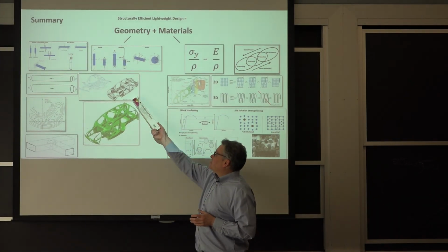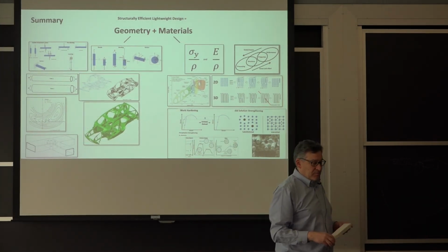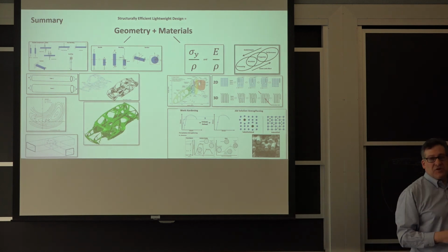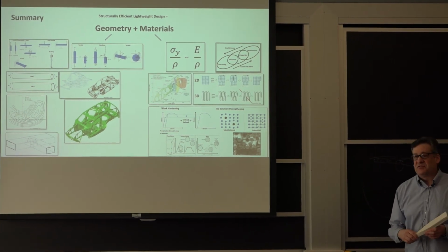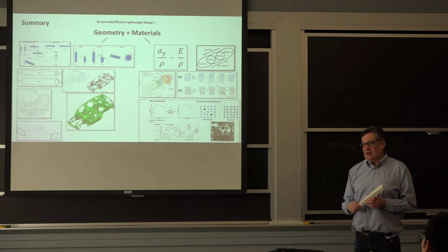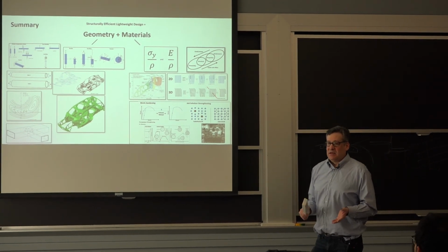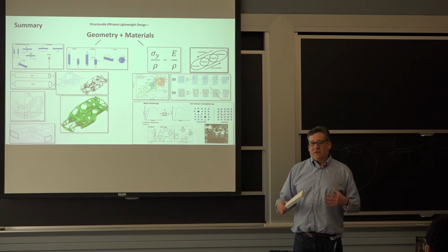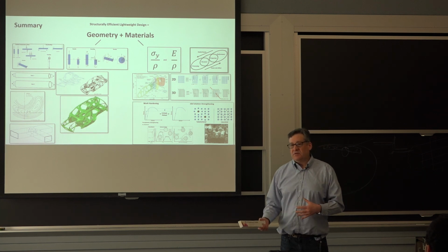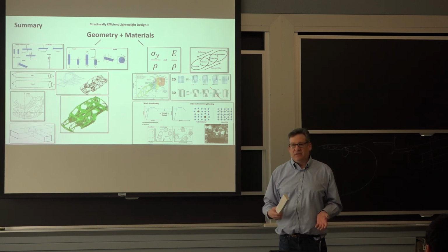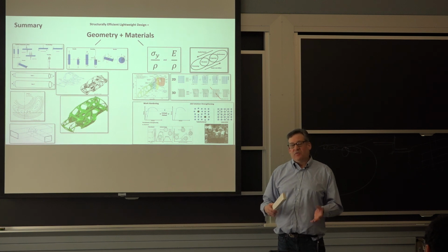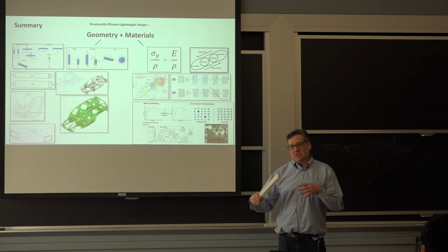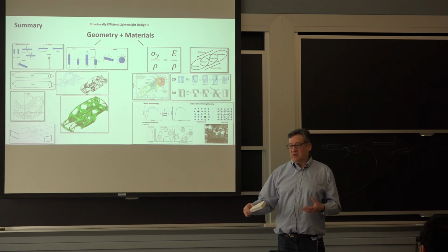We took a complicated structure, a car body in white, the primary structure of a car, which looks very complicated on the surface. We broke that down into various beam elements. These various beam elements can be simplified. You can determine what loading cases are on those out of the bending, torsion, tensile, compression. And then through knowing that, you can design each of those parts to take those different loading modes or choose materials that make sense from a cost perspective.